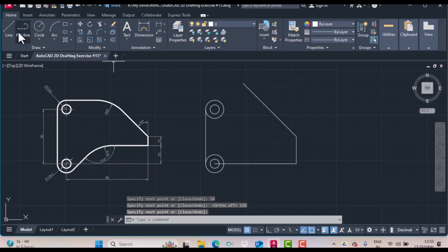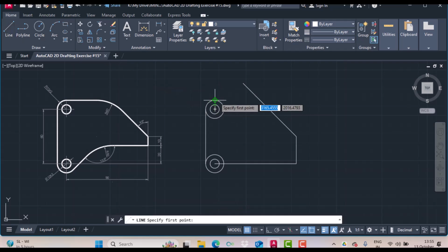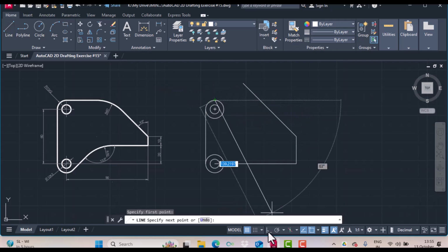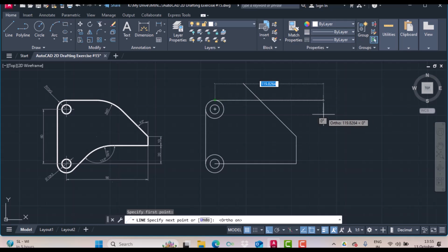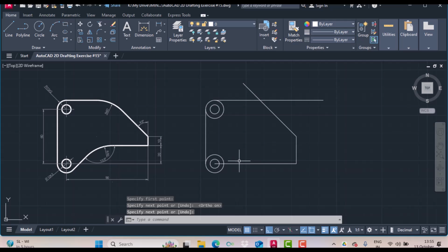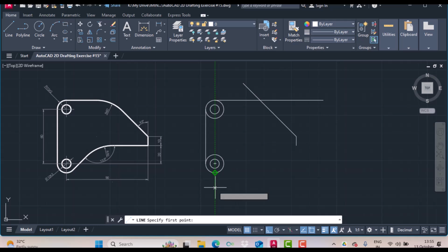We also draw one more line quadrant to this, turn the ortho on, intersecting this line, and hit enter. Now coming to the most important part of this drawing, we delete these support lines at the moment and then draw one line randomly from here of a random length.